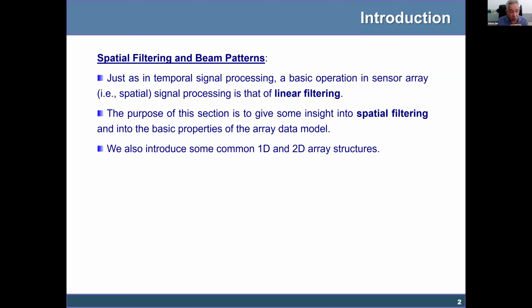So you try not to attenuate, or even to amplify, the frequency components where the signal dominates, and where the signal is negligible and there is only noise, you try to attenuate as much as possible. In this way, you try to eliminate the noise components outside the bandwidth of the signal. This is the purpose of temporal linear filtering.